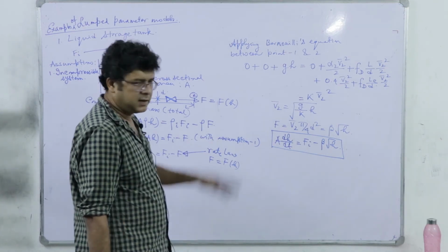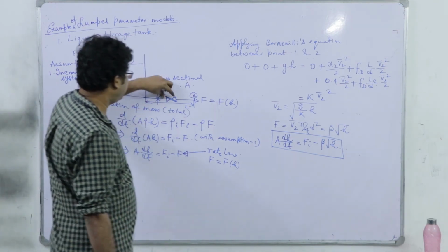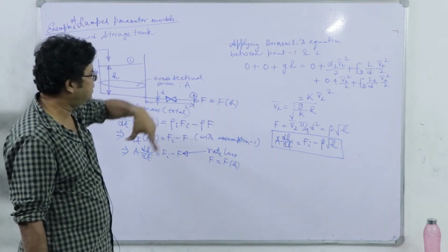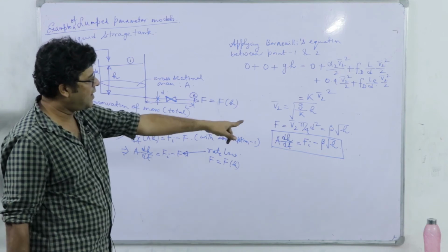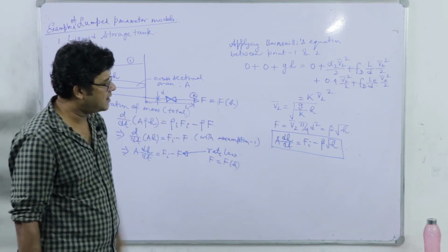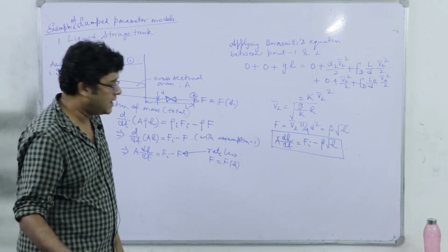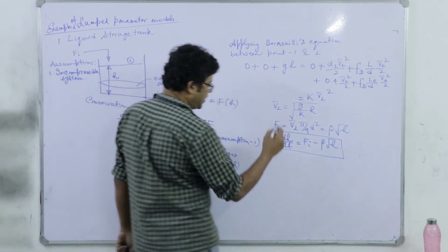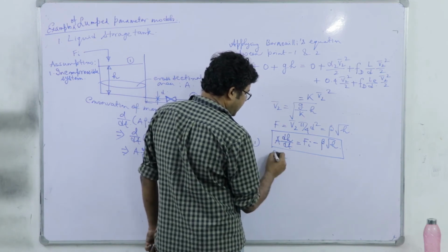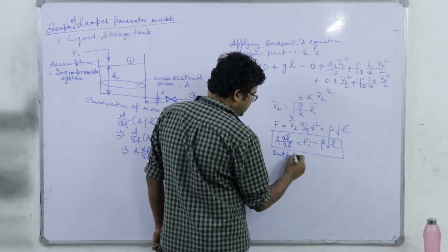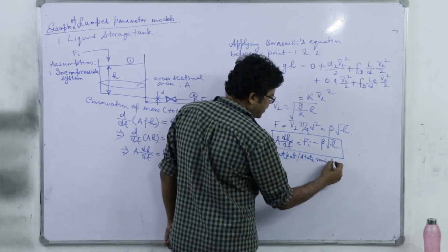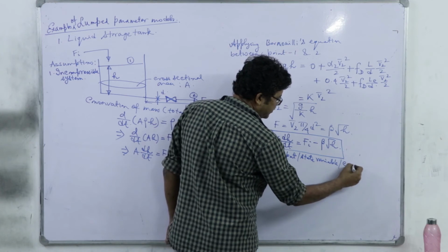So beta is dependent, precisely, on the opening or closing of that gate valve. If I am given the system or the state equation just as I have marked it, now let's identify what are the input and output. First let's write the output, which is the state variable also, and here this is also my control objective.